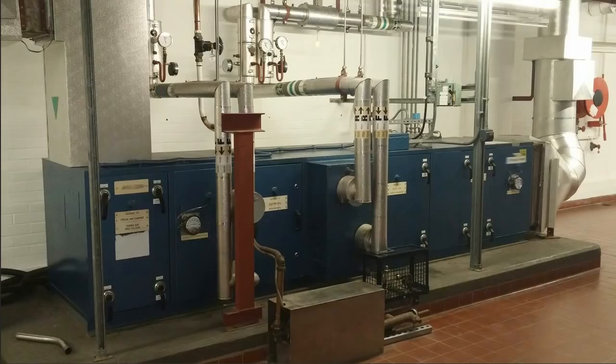So just to show you some examples of what AHUs might look like in the real world, here's just a few examples of ones I've been working on over the years, and you'll see here this is a very small AHU. It's only supplying one room, kind of a medium-sized room, but it's got the same setup as a larger system, although this one is just recirculating the same air within the room, and there's an extract elsewhere for supply for fresh air. But this one, it's just bringing in that return air.